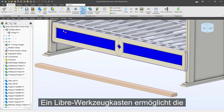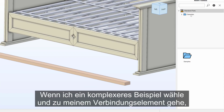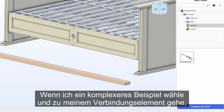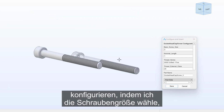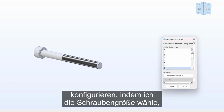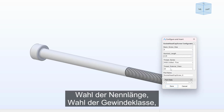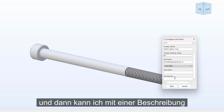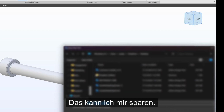The Alibre Toolbox allows a variety of parts to be configured in a variety of ways. If I choose a more complex example, and I go to my fastener, I can configure a socket head by choosing the screw size, choosing the nominal length, choosing the thread class, and then I can save with a description and part number if I'd like to. I can save that out.